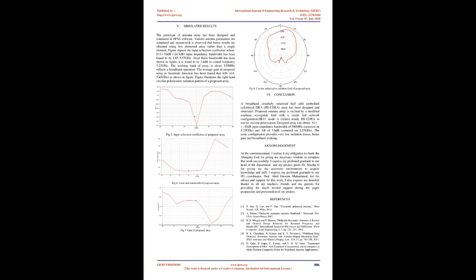Step 5. Design and implement array configuration. A two-element DRA array is to be designed and simulated. The parameters are the distance between array elements, d; feed point positions, xf; width of the feeding strip, w; and Z0, the impedance parameter.